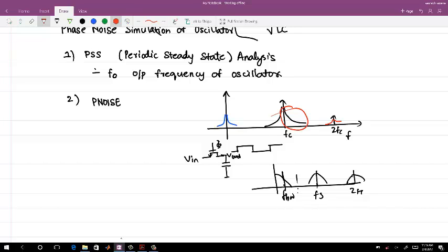Phase noise, it's not that phase noise is single sideband. We always treat single sideband for our analysis. Okay. Phase noise exists around the carrier on both the sides. So any system which you are using will be a narrow band around the carrier, right? So the noise you should consider is plus and minus delta around the carrier. In all these cases, because you are having a symmetry around the carrier, that's why you only treat a single sideband noise. But for the total noise analysis which you are going to do, you add 3 dB to this number. Right.